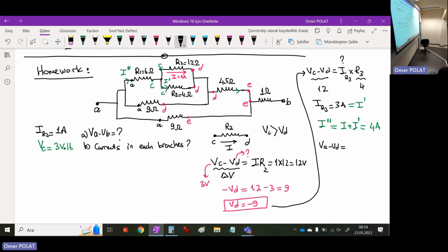I know this current. If I write here the total resistance, I can calculate. So current flows through this total resistance. What is the total resistance? I double prime times R1, 2, 3, their combination. Three resistors times the current I double prime, which is 4 ampere. What is R1, 2, 3? These are in parallel combination, in series with R1.